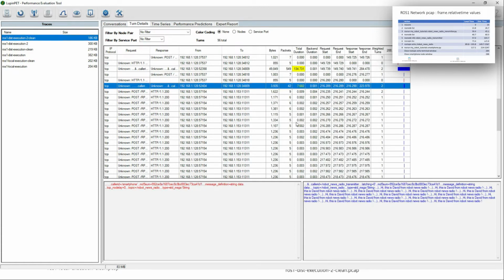So it looks like it's talking directly between the publisher and the subscriber nodes. After it's done its setup using the ROS master, it looks like it just falls back and talks directly, sort of inter-process communication between the two nodes, which is good. And we can see it happening here. The other interesting thing in here is this one actually stopped. When I stopped the subscriber node at 223 or 224 seconds, it seemed to actually stop the subscription activity.